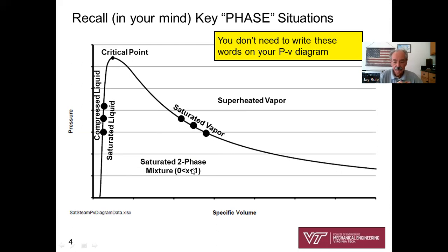It's a mixture of, let's say, H2O, water, saturated liquid water, and saturated vapor if you're under the dome. If you're on the dome, if you're laying on the dome on the right-hand side, you're a saturated vapor. You couldn't see that with your eyes, but you'd be a saturated vapor. If you're laying on the left-hand side of the vapor dome, you're a saturated liquid. At least that's what you can see with your eyes.